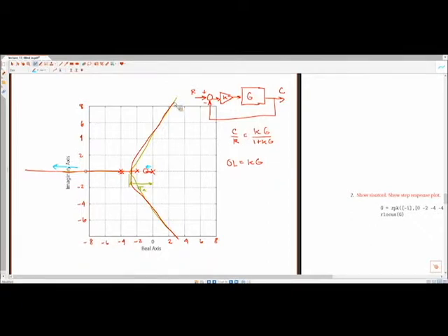Yeah, exactly. So that's a good segue into the next point, that we have these two branches. This is where the closed loop poles move as k gets large. So if we increase k too much, eventually we're going to find a value of k such that the closed loop poles are in the right half plane, right? So if we get perfect cancellation, you have to have k equal to infinity here. That's not going to be possible for this specific system.